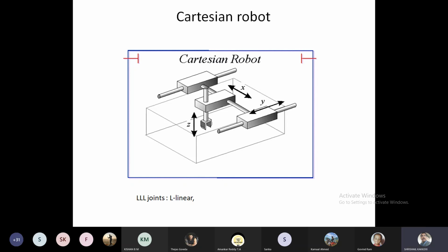A simple example you can see: you just stand and stretch your hand and turn around your body. An imaginary cover or envelope will be generated around your body, and it is the work envelope. That means within this you can flexibly work. If you go to a hotel, the server will not give the food to another table. He will give it to your table, because you can stretch your hand and eat. That is your work volume. Within your work volume, you can flexibly work. In a similar way, the robot can flexibly work within its work volume.